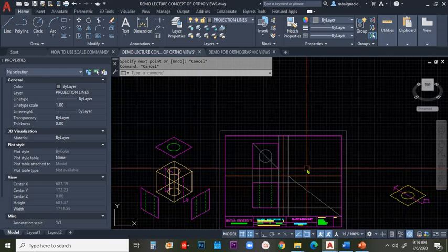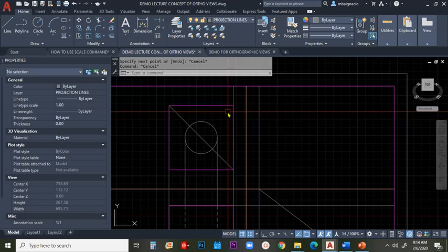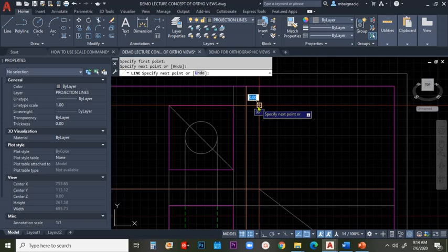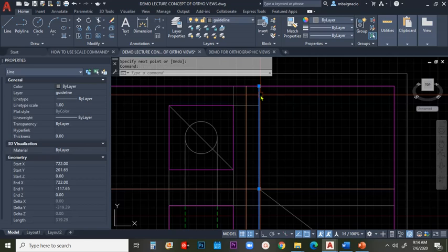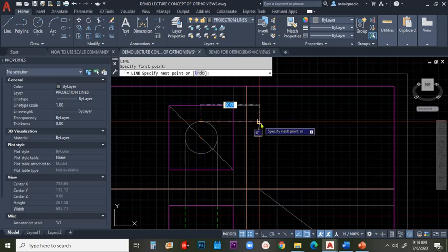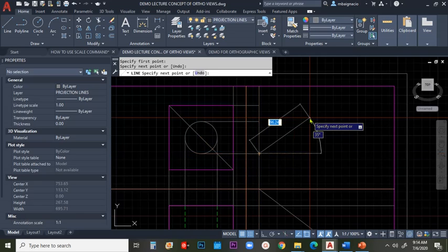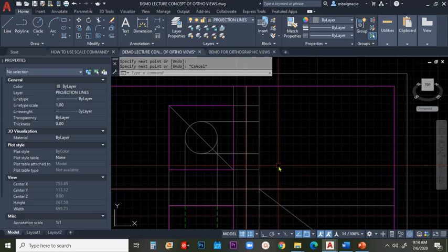Now for the view on the side, we go back to top view. Okay, so let's consider these endpoints here on the side. So this is the right side view plus the opening. Okay, so this is what you're going to do. Create a line passing through at all points, touching the another set of offset from the center at 15 mm. So another line passing through here, perpendicular there, and then another line passing through here, perpendicular there, and then another line here at the end point passing through here.